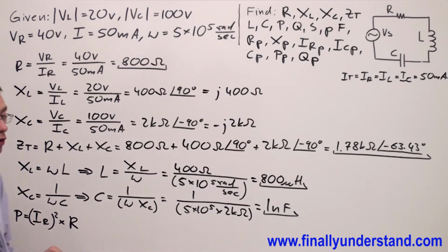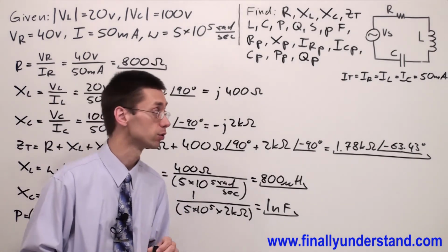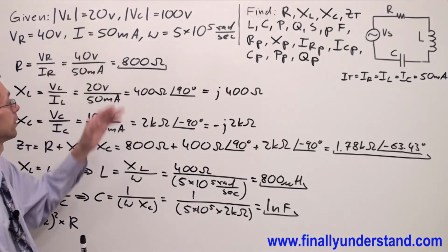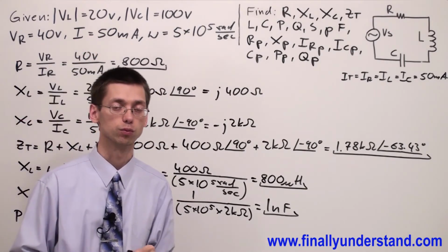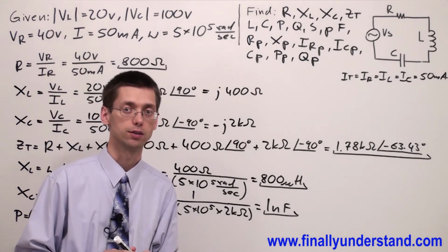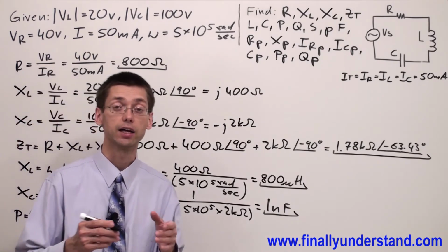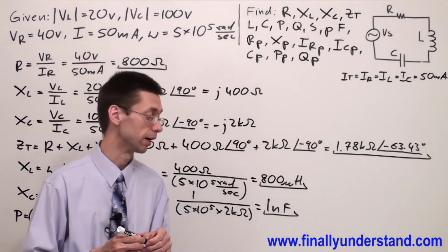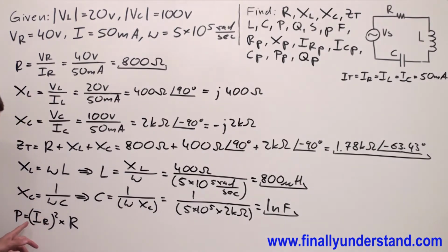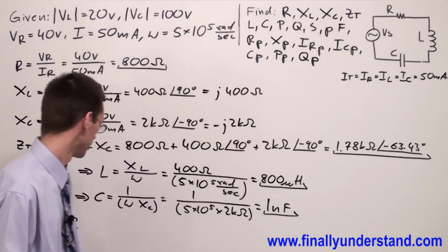Because this problem is not saying that I'm supposed to use peak values of voltages or current, so automatically I assume that this is RMS. If your professor, or the book, specifies that it has to be peak value, you're supposed to use 1/2, but if it doesn't say anything, most of the time this is going to be RMS. So